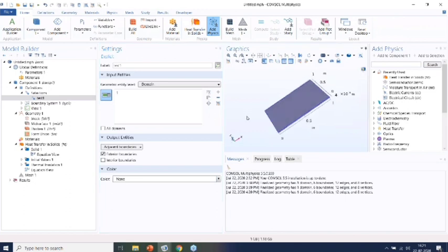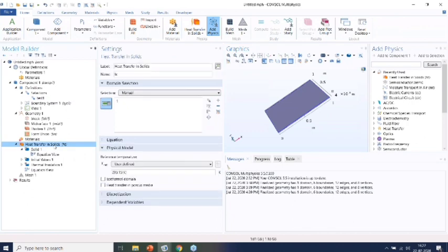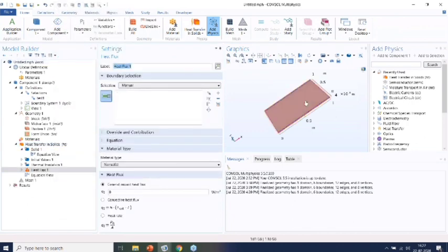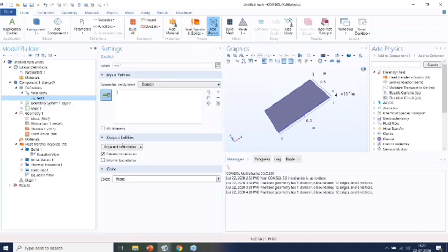In that case, if you are selecting two different domains, it could be interior boundaries, or exterior boundaries, or you can have both selected. Here in this case, let's say I'm just having exterior boundaries. Now, if I apply any boundary condition, let's say heat flux, rather than selecting each and every boundary separately, I can select this text one. Please notice that earlier I didn't use these output entities as boundaries.